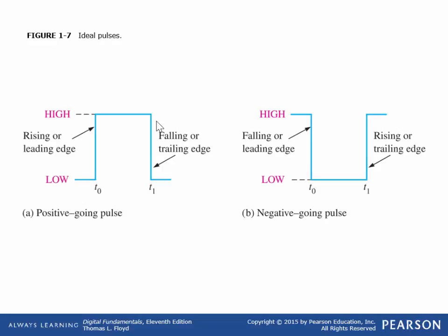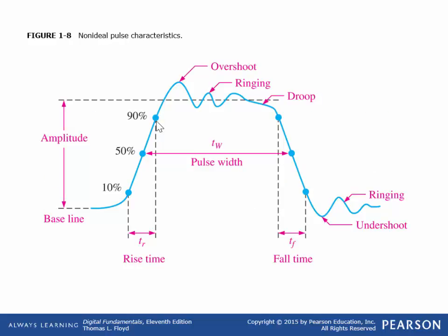We have a couple other terminology items we're going to go through here. We have rising or leading edges, and trailing or falling edges, on digital clocks. We're not going to be using clocks for a while, but we'll come back to this. That's the ideal clock, what you normally see with an oscilloscope. That's a pretty dirty clock, but I've seen them that bad. The reason is that you've got resistance on the board, capacitance, and inductance, and you're going to end up with some oscillations.